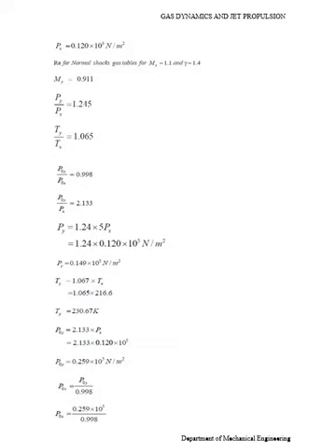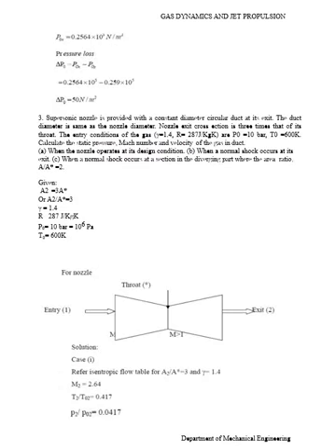Similarly, P0y equals 0.259 bar and P0x equals 0.2564 into 10 power 5 Newton per meter square, or bar. Therefore, the next one, pressure loss: pressure loss equals P0x minus P0y. Then finally, the pressure loss equals 50 Newton per meter square. Okay.